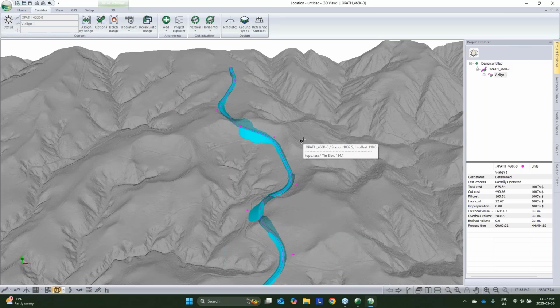We work with, our clients work with drone data, fixed wing LiDAR data, satellite DEM data, and with that, there's a whole spectrum of accuracy and costs associated. There's some really detailed satellite DEM data that you can get, and usually that comes for a fee, but it's still much cheaper than a full LiDAR acquisition of the area. But there's lower resolution satellite DEM data available globally. The SRTM data set's one example, and we connect to something very similar to that in terrain.